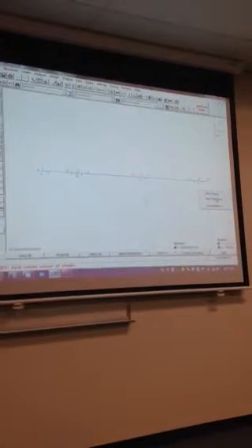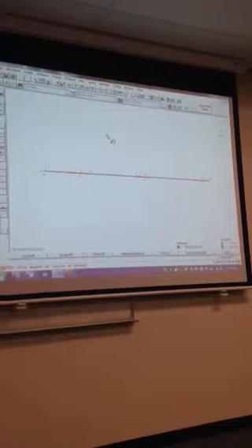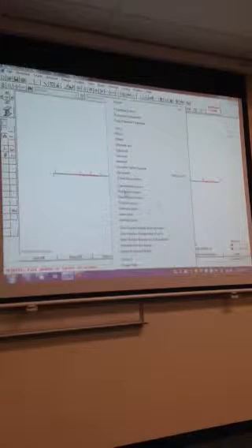The loads are pretty simple. If we left click and create a box, and left click down the bottom and select members, that's selected all the members. Now we can change those or whatever, but I'm going to right click and that gives me a menu, and we're going to go down to distributed forces. Okay?